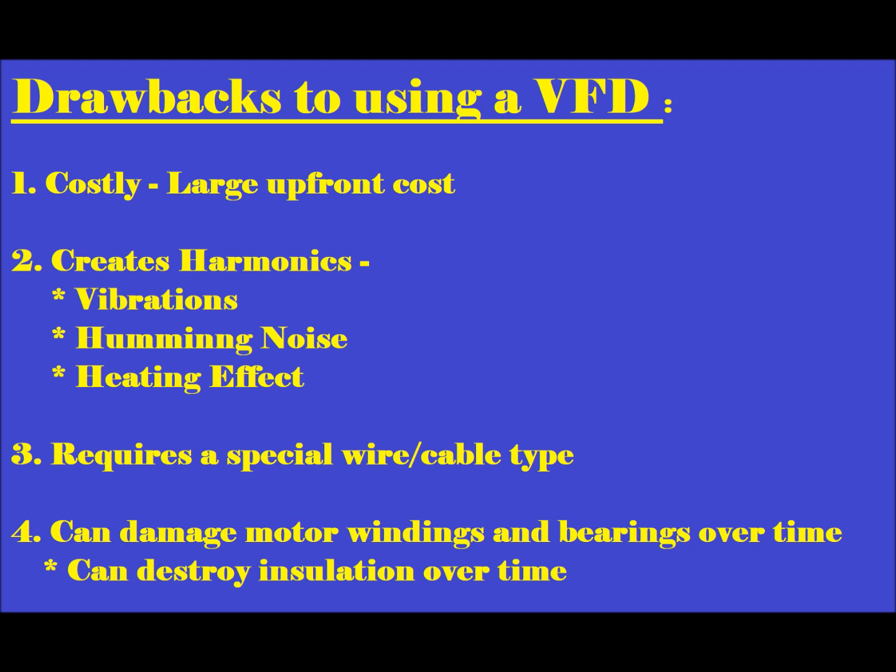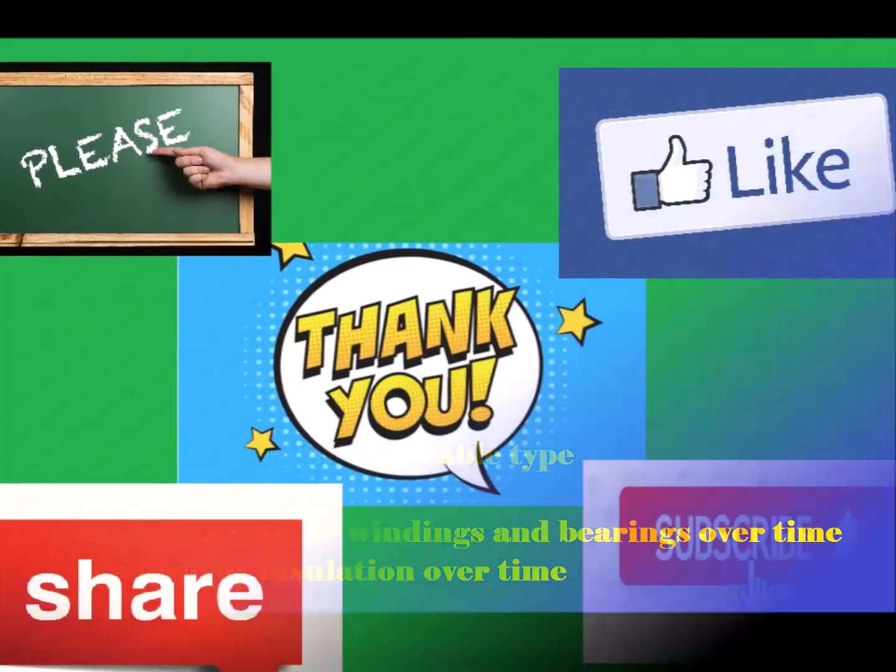And we'll come to the fourth point, which is also similar. Since harmonics are created, we have a different frequency. It can damage the motor winding and bearing for sure, and it will destroy the motor.